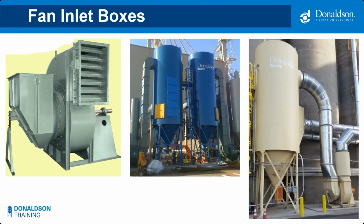Well, this is where that inlet box that I mentioned before comes into play. You'll notice on that photo on the left, there's that inlet box. And inside this inlet box, at least on larger inlet boxes, are engineered turning vanes to help direct the airflow and keep it linear as it enters the inlet of the fan.